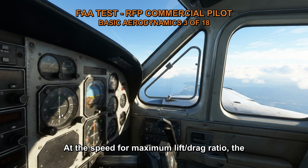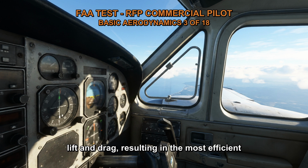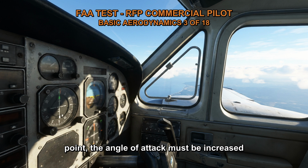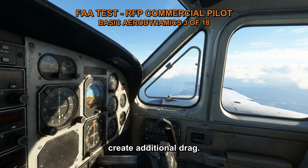At the speed for maximum lift/drag ratio, the aircraft is operating at an optimal balance between lift and drag, resulting in the most efficient flight. However, as the airspeed decreases below this optimum point, the angle of attack must be increased to maintain lift. Increasing the angle of attack to generate more lift also increases the lift-induced drag. This is because a higher angle of attack produces stronger vortices and greater pressure differences, which create additional drag.